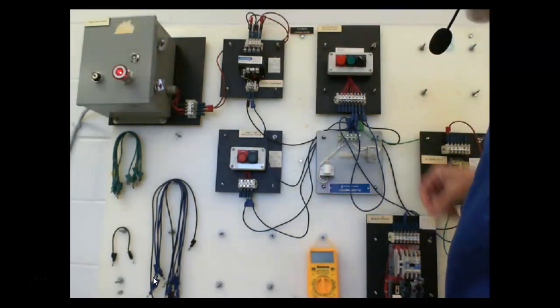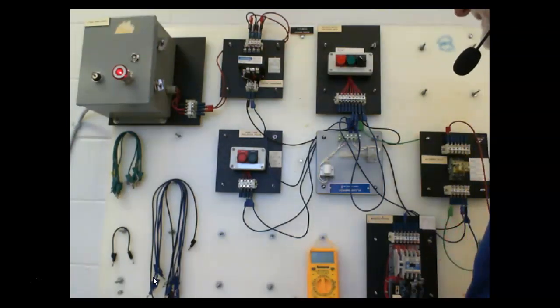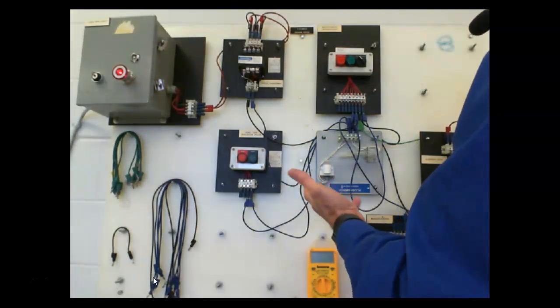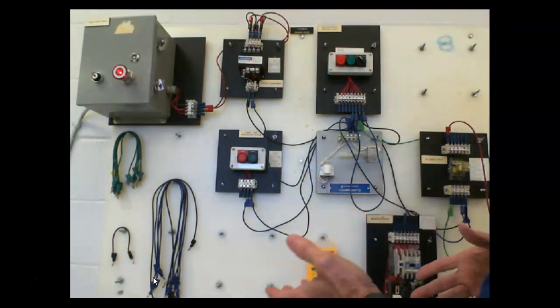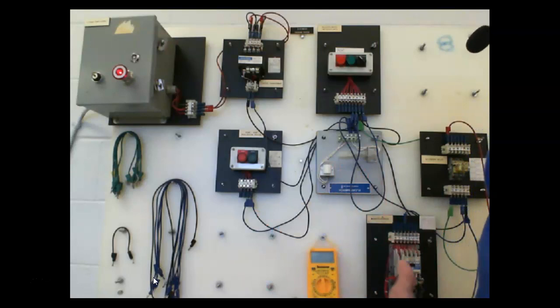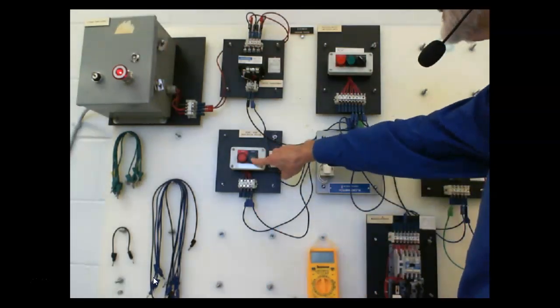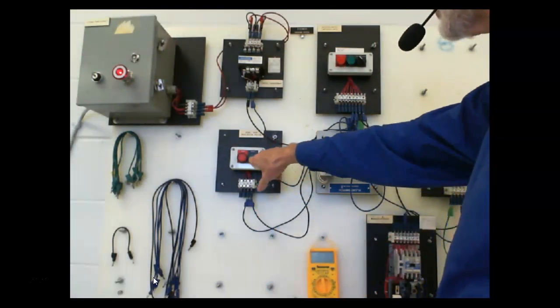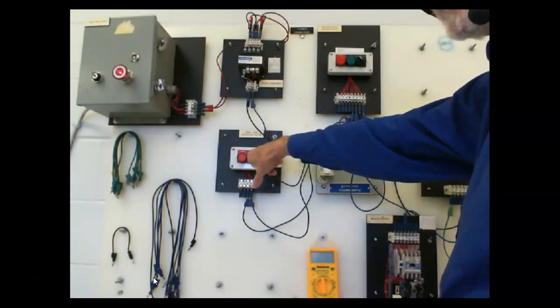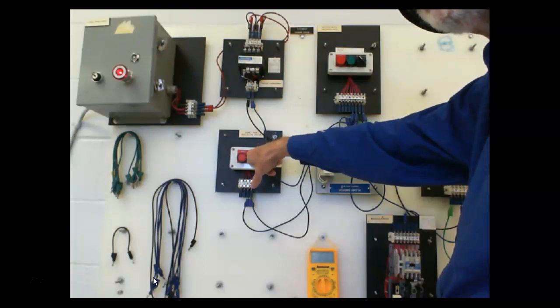Yeah, so here's the hand position. So the motor starter's out. With the hand position, I'm supposed to be able to manually run the pump. The other one, the pump is going to be controlled by the level switch. So right now I've got it in hand, and I come over here and press my manual override, or my start button. So now I'm controlling this manually.